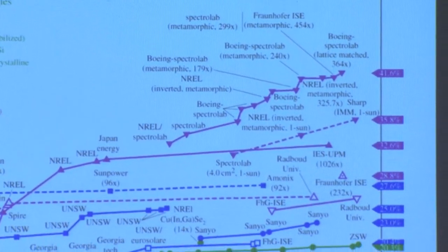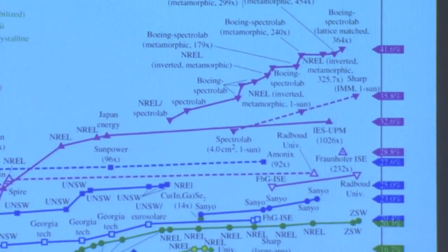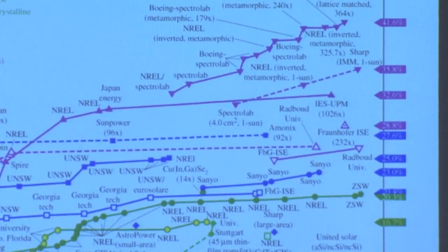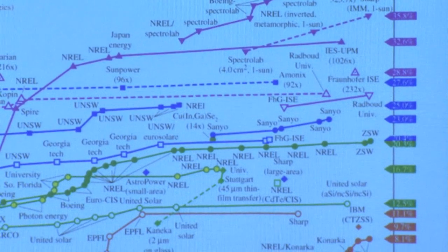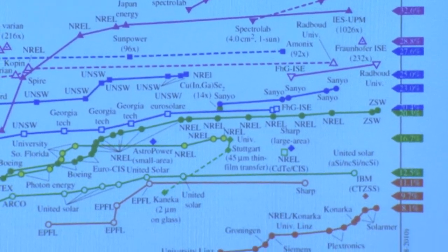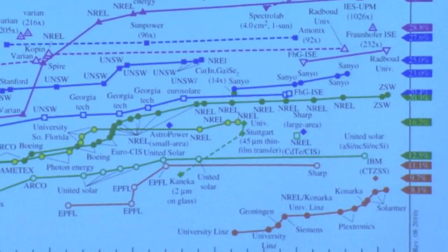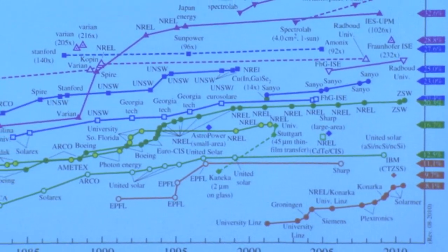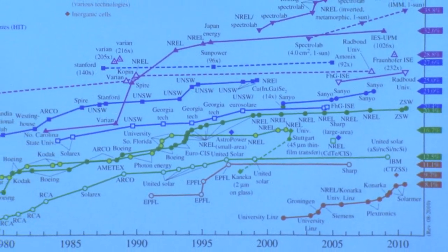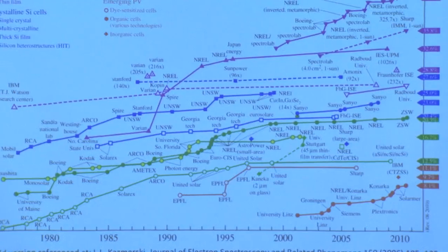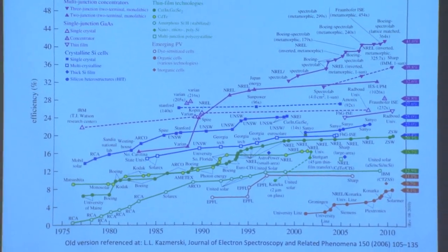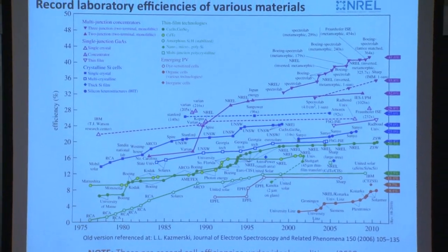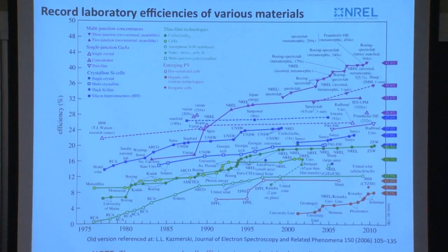It has been done in the past that people would do an HF dip of their silicon-based solar cells right before measuring the efficiency. The hydrofluoric acid would result in surface passivation, but of course it would result in a very low surface adhesion of the metal. So the metal would flake off afterwards. It wouldn't pass a tensile test, but you would nevertheless achieve instantaneously higher efficiency. Those practices have largely been weeded out. These were the early days when it was the Wild West of solar cells.